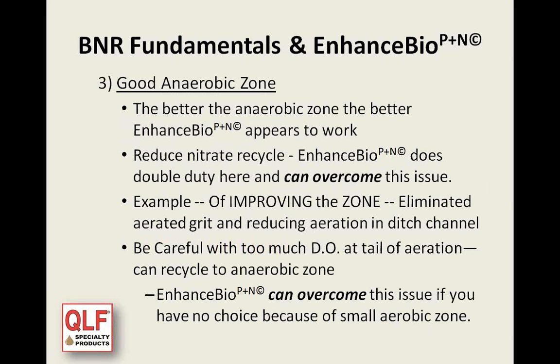Good anaerobic zone. It appears that the better the anaerobic zone is, in other words, the less nitrates and oxygen that are coming into that zone, and the right detention time, those all create a good anaerobic zone. The better that anaerobic zone is, the better our product works, the less product it takes.